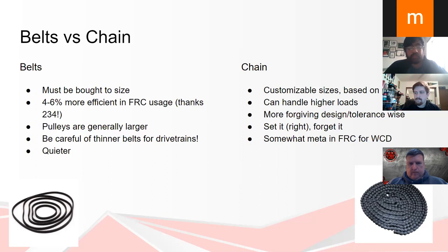The thing I like most about it is once you get it right, once your center distances are fine, you've got the right chain and you've tensioned it if you need to, you can almost always just set it and forget it when it comes to drivetrains. Due to that, it's somewhat in the meta in FRC for tank drivetrains, for the West Coast style drivetrain we were talking about earlier. So personally, at Ferrodermis, this is what we use most of the time, chain.